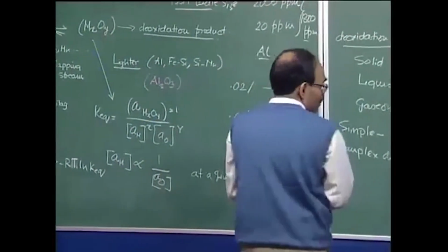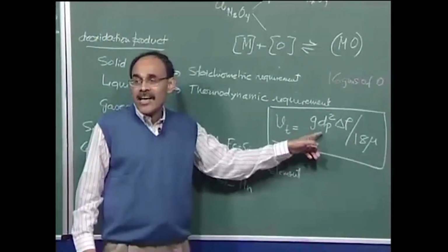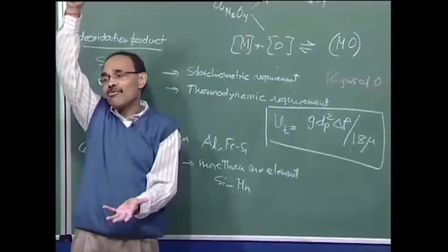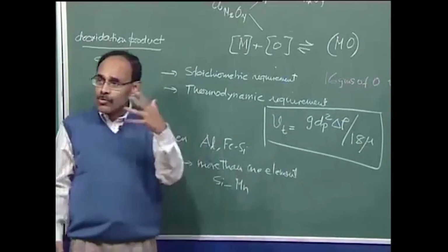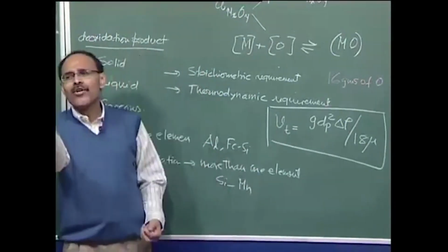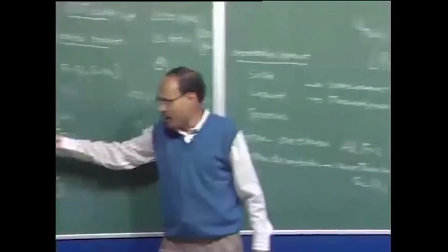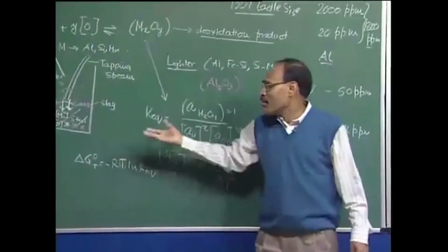Coming back to the Stokes law of settling, given the size range, and if I know the bath height, I should be able to find out the possibility of inclusion flotation. We can calculate and show that if the inclusions are of the order of 40 to 50 micron size, they virtually have no possibility to rise up and float to the free surface.